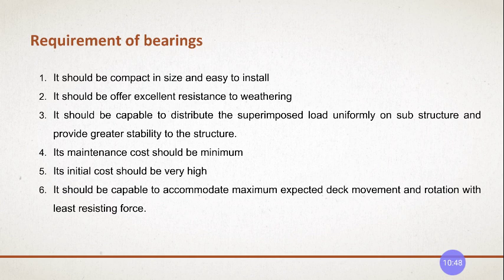Right? So it is a moving part. It moves along the direction of motion, or due to the temperature changes or angular movements, it moves. So the maintenance of this moving part of the structure becomes very high. It requires a huge amount of maintenance, regular maintenance work and checkups.